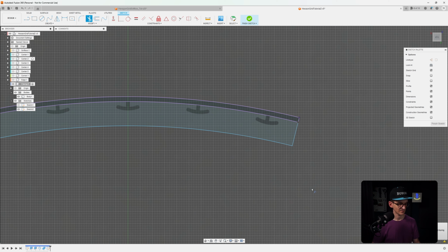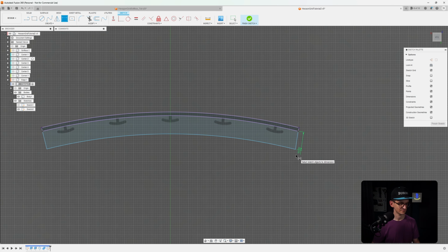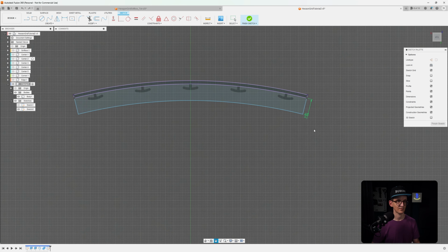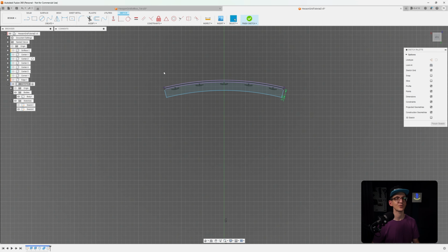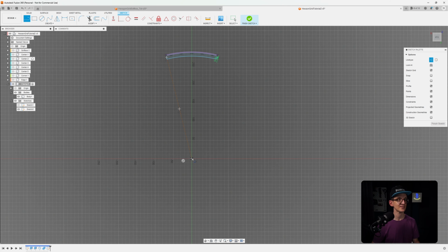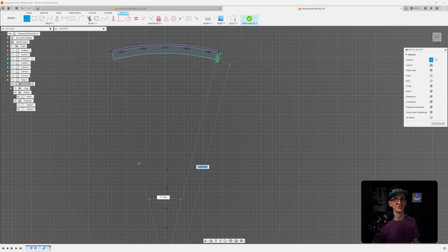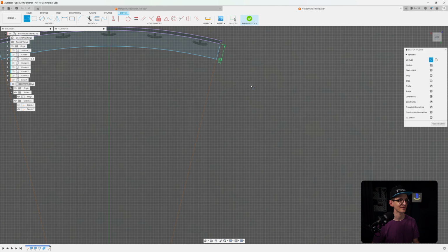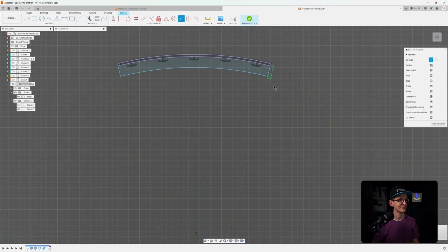Now it's not yet defined, of course, but we can give it a definition. So the lip should be, maybe a centimeter thick. Oh. And it lost its constraints. So again, we add the constraints back. So we add constraint lines, construction lines, I meant, holy crap. And we make sure, okay, this is still fine.